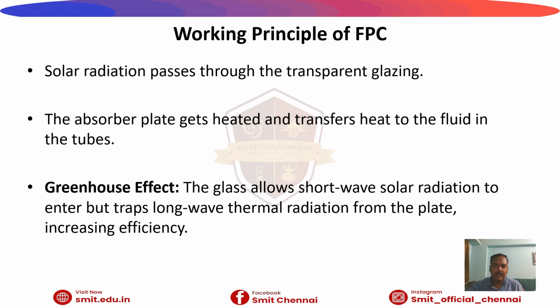The working principle of FPC: solar radiation passes through the transparent glass, and the absorber plate gets heated and transfers heat to the fluid tubes. Here, the greenhouse effect is happening. The glass allows short wave solar radiation to enter and traps the long wave thermal radiation from the plate, increasing efficiency. So here we are using the greenhouse effect to retain the heat energy.